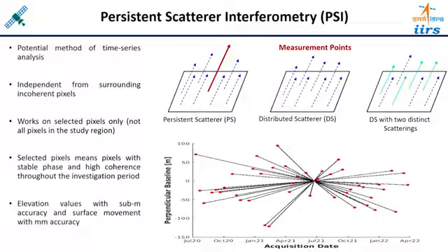Okay. But yes, if you are applying this technique over an urban area, where buildings are there, those buildings are not changing very frequently, so this technique can work over urban areas for a longer period also. So this technique is applicable and gives accurate information over man-made structures, or you can say urban areas. But for the natural environment and for a longer period, it will not work, because sufficient PS points you will not get.